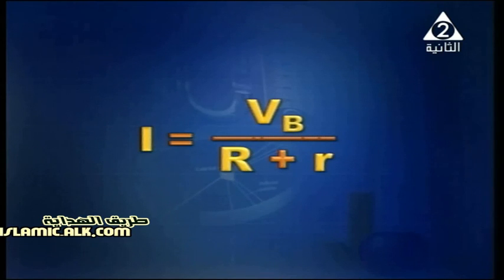And what about the relation that expresses Ohm's law of the closed circuit? Of course, the current through the battery, the main current, equals V battery over R capital plus R small. R capital plus R small means the total resistance of the circuit: the external resistances as well as the internal resistance of the battery.